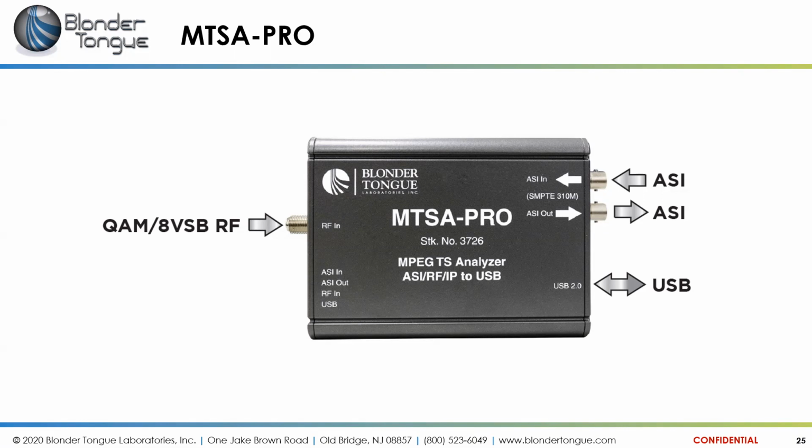Again, I'm from the RF world coming into the IP world for IP television, and I still see it from the RF side. One piece of RG6 or RG59 coax can handle many more channels of video than a piece of Cat 6 can, in my eyes. Which is again why I don't think IP television is going to overtake cable television, CATV, coax cable in the near future anyway.